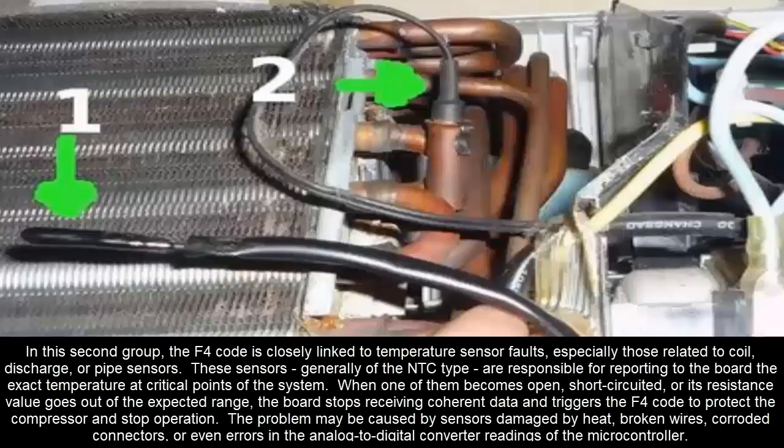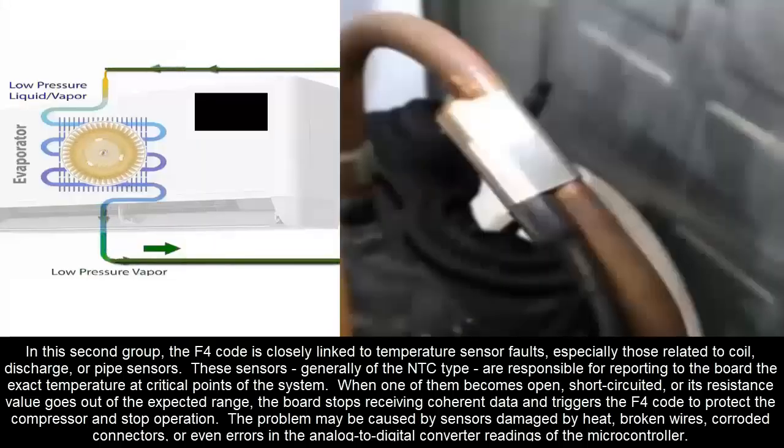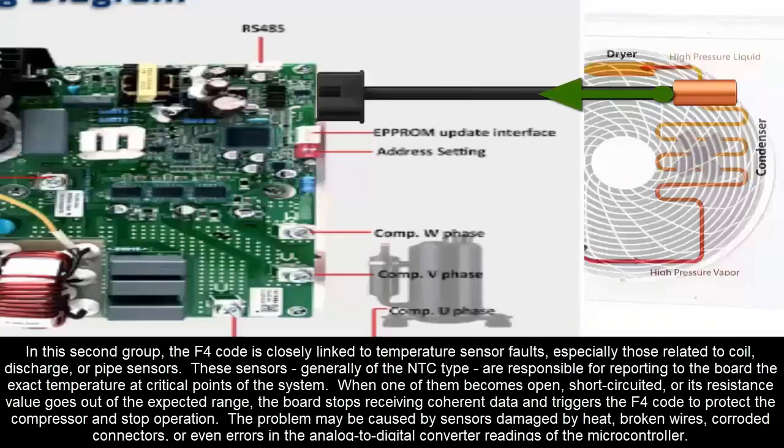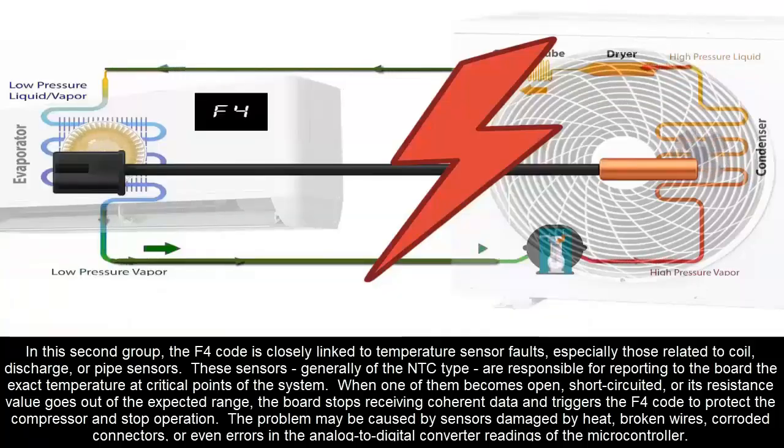These sensors, generally of the NTC type, are responsible for reporting to the board the exact temperature at critical points of the system. When one of them becomes open, short-circuited, or its resistance value goes out of the expected range, the board stops receiving coherent data and triggers the F4 code to protect the compressor and stop operation.